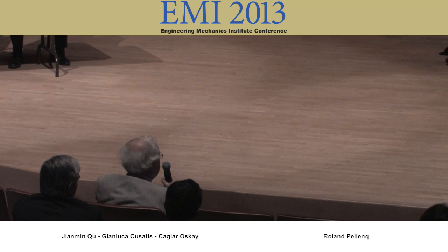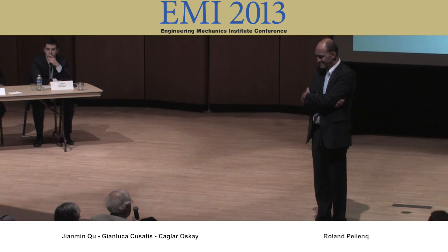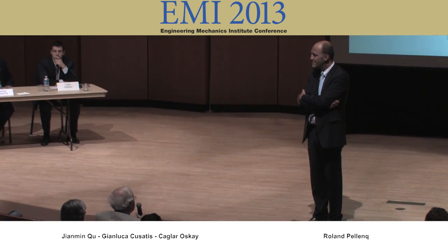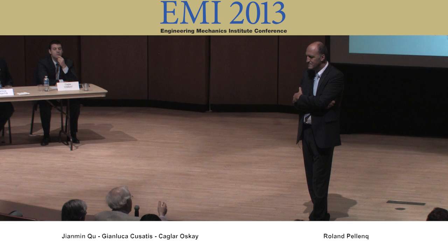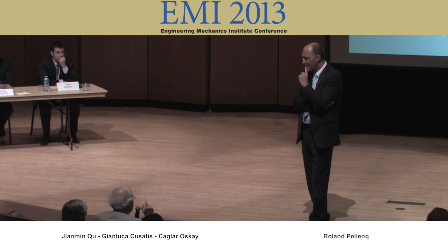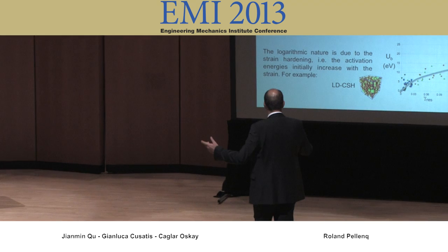Yeah. Now, of course, there is also a sort of microprestress, as we call it: stresses in the structure on the nanoscale, and they relax. This has been used to show that the long-time creep is actually logarithmic, because as they relax, the rate slows down. So are you dismissing that mechanism, or is it on top of what you argue? Is it both? Between the nanoscale and, of course, the creep, we know in cement it must be due to shear slip, affected by transverse stresses. Otherwise, we would see a change of stiffness. We don't. Of course. Okay.